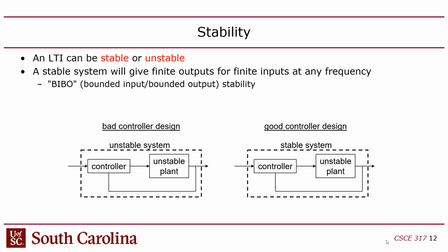Now, if you have an open loop control system, it's just the two transfer functions convolved, right? Multiplied together. If it's a closed loop transfer function, you also will have this internal connection, which I'll talk about how to realize mathematically. But from the perspective of the whole system, controller plus plant, you just have one input, one output here, right? And you want that system to be stable. You want it to be bounded input, bounded output, stable.